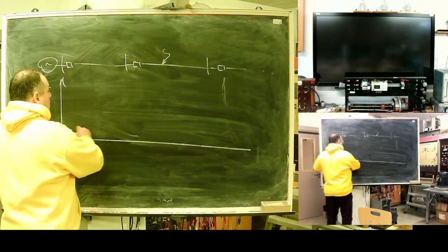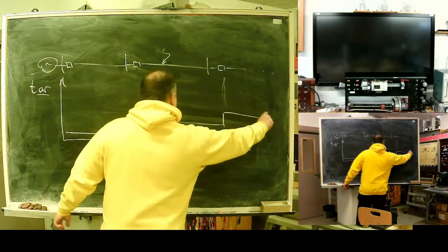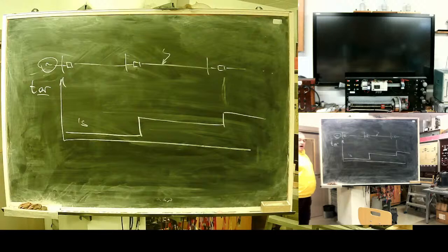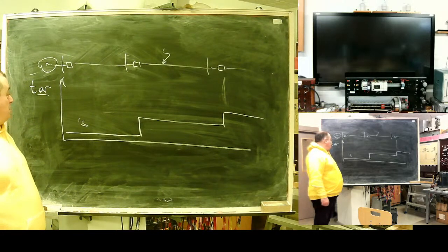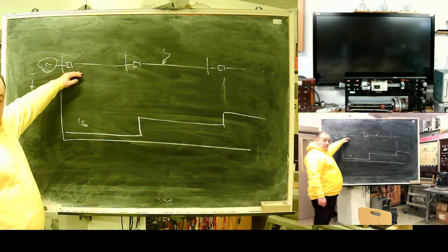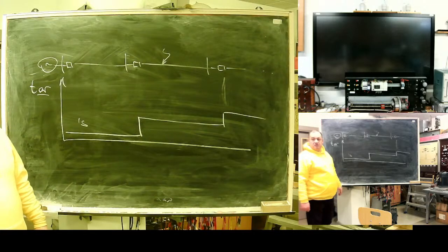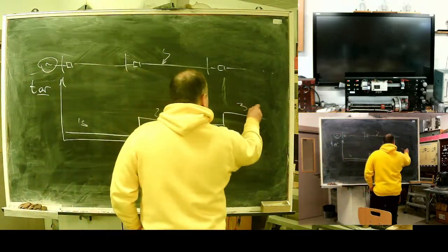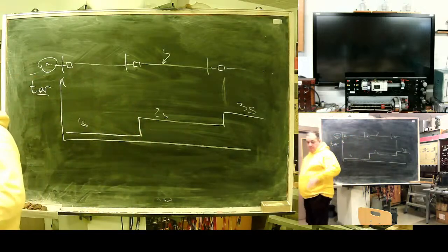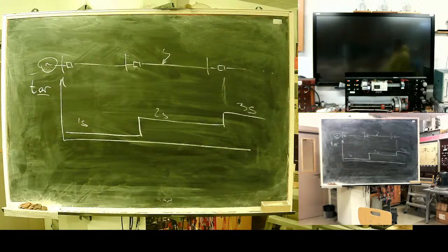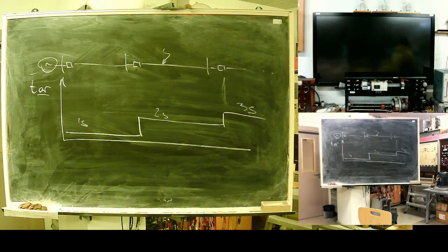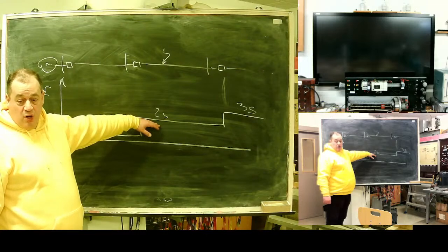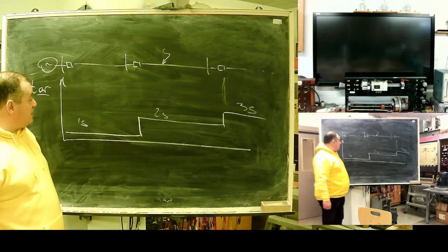Switch this one. 1, 2, 3, with a step of approximately 1 second. So after the fault is cleared, the first segment will go back in 1 second. Sometimes the time is taken short. This one in 2 seconds, in 3 seconds. Boom, boom, boom. They will be switched back. If the fault is persistent, as I showed, the first segment switches without problem, the second segment switches onto the fault immediately, disconnects, and everything stops.